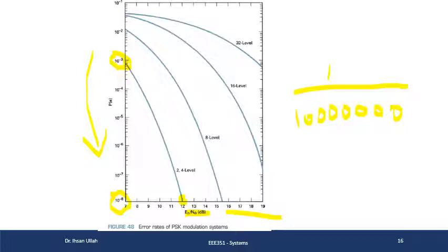10 million, okay. So this is a very good rate that you have. On the other hand, if we look at 32-level PSK, if Eb/N0 is 19 dB in this case, it is equivalent to the bit error rate in such a case being equivalent to 7 dB, Eb/N0 7 dB for BPSK and QPSK, okay.